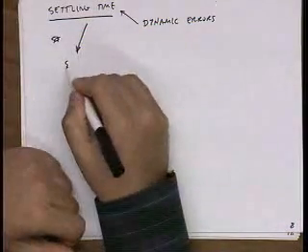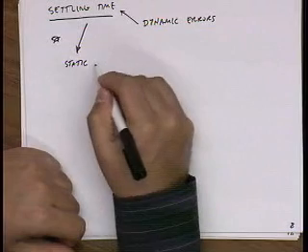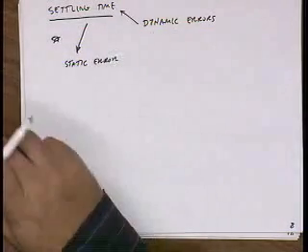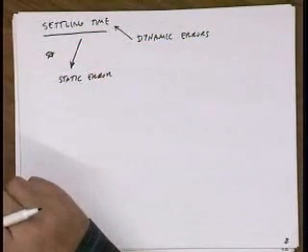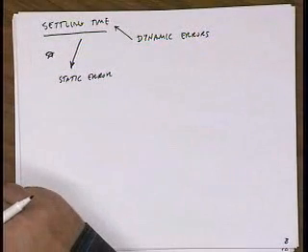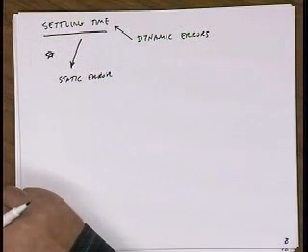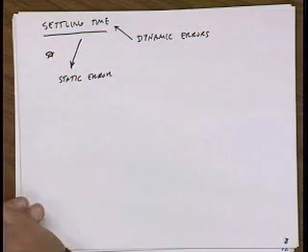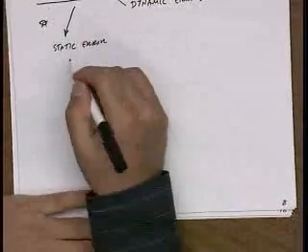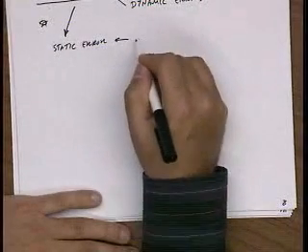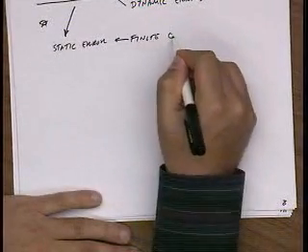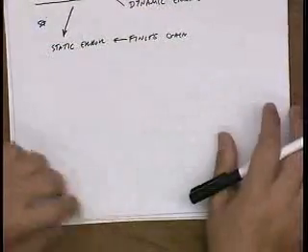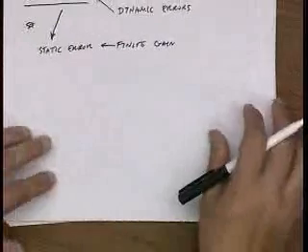Well, a good name would be a static error, right? As opposed to a dynamic error. But where do we get static errors in amplifiers, integrators, other circuits? Just the gain, if the open loop gain isn't high enough. Yeah. So the static errors are due to offset and finite gain. Someone mentioned offset voltage. That's right too. That's something we just talked about.